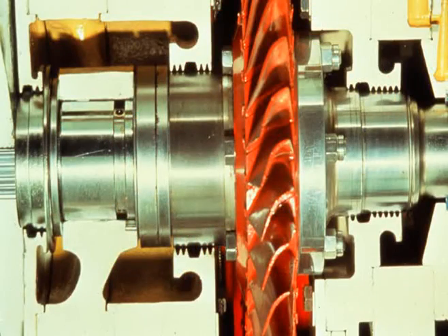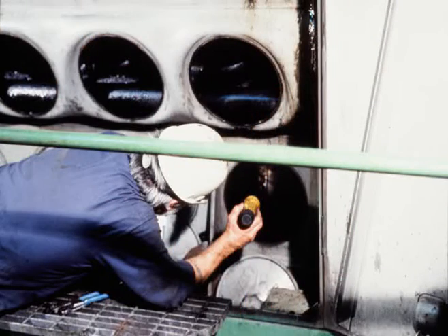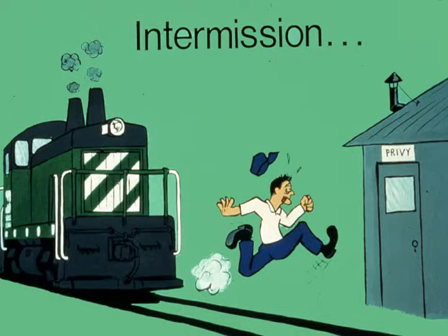Following any shutdown, the pump will again run for about 30 minutes to remove heat to extend the life of the turbocharger bearings. This system should also be qualified following any maintenance or any extended shutdown. This completes our description of the EMD lube oil system components. Discuss this with your instructor.